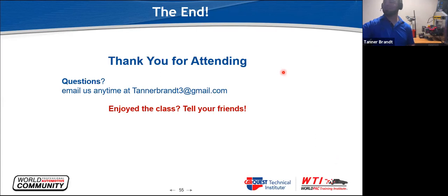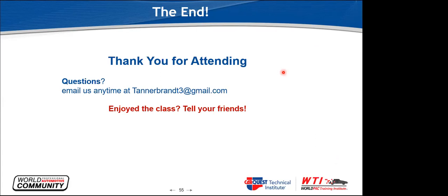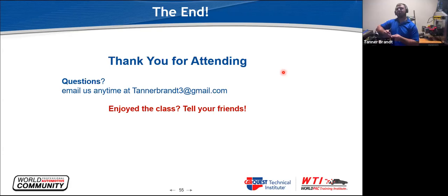Nobody's got questions. I actually do have a question that has come up a few times recently, and it's more with aftermarket stuff, but I've seen it a few times on some of the diesel stuff. I know, like with some of the bigger aftermarket turbos you get into on tuner cars, stuff like that, you'll have anti-surge ports in the compressor housing. I've noticed the same kind of thing on a few of the diesel turbos. Is that just to, I know obviously we have throttle plates and a lot of the diesel stuff we're seeing now. Are they serving the same purpose, or is that more resonance? What are those ports generally for?